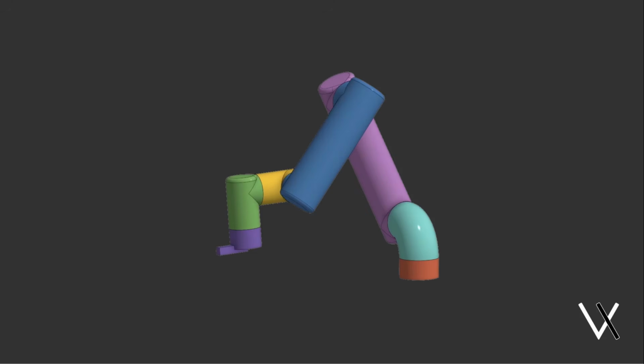If we take a look at the robot mockup from video 2, the two types of transmissions should make more sense. Here you'll see that sections 1 and 2 are pretty compact, sections 3 and 4 have plenty of space, and sections 5 and 6 are also pretty compact. Importantly, sections 1 and 2 are by the base of the robot, which is the farthest away from the payload, so they'll have to output the most torque.